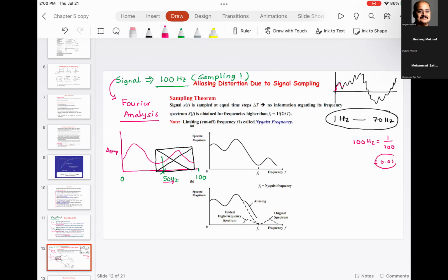So every 0.01 second, you are capturing a discrete point, a snapshot, and then you feed that into your FFT, some type of Fourier transform algorithm. Once you feed it to the FFT, you get these nice plots, these nice peaks. FFT will give you frequencies and amplitudes.